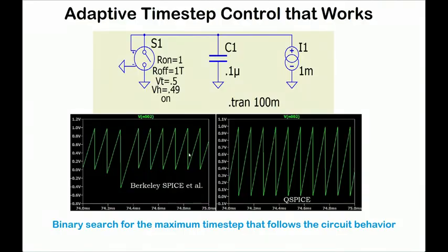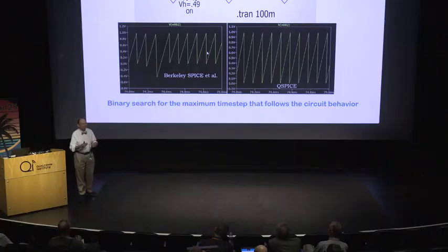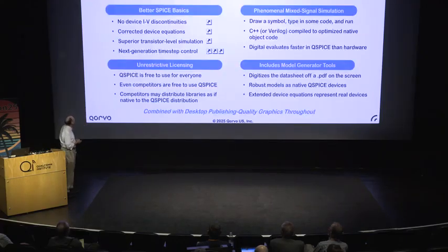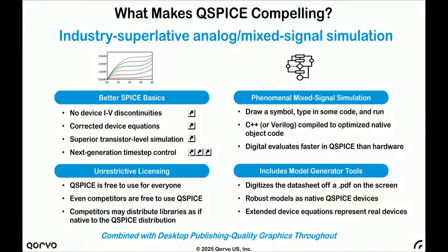Now, a lot of SPICE programs can't simulate this. For example, PSpice doesn't have a hysteretic switch, and that was to avoid this behavior because they knew they couldn't solve it. The algorithm used in SPICE requires continuous value and slope, and a hysteretic switch doesn't have that. So in the head frame of SPICE, it seems like it's non-physical, but it's not. You can buy a relay, and it's hysteretic, and it trips or not. And that problem is simply solved. I mean, it's something you can simulate. Okay, so that's one aspect of time step control.